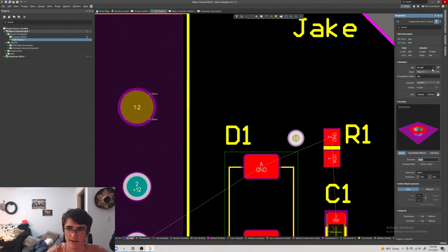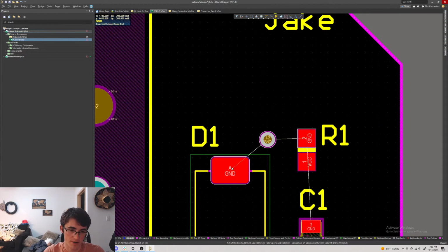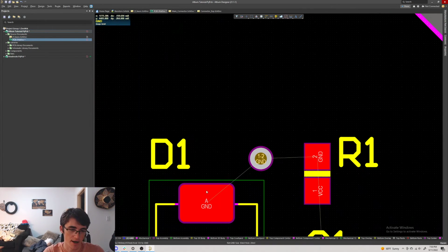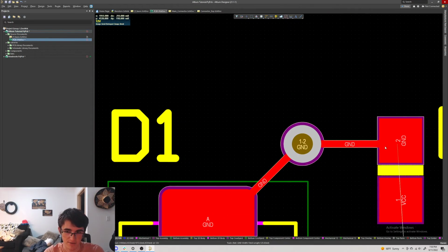So you double click on it, and similar to all other parts, it might have a net assigned to it, and you want to pick ground. And then you'll see here, now that this identifies as ground, it will auto select to these two pieces instead of the connector. You want to make sure you're on the top layer, because these two parts are highlighted in red. You press Control W, and then click to them, just like that. Now there's no highlights to them.